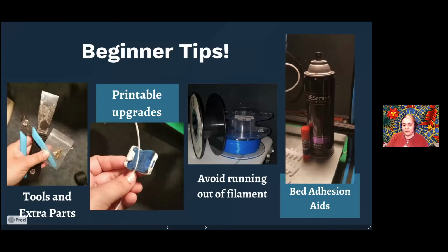Running out of filament is bad news. There's nothing worse than coming in and finding out that your print stopped, or your print is still printing because it thinks it has filament and it actually doesn't. My printer has an auto sensor to tell if it's run out of filament. It doesn't work, so I've actually pulled it off my printer. It's just not functioning for that. It continuously tells me I'm out of filament, so just making sure that you don't run out is pretty simple.